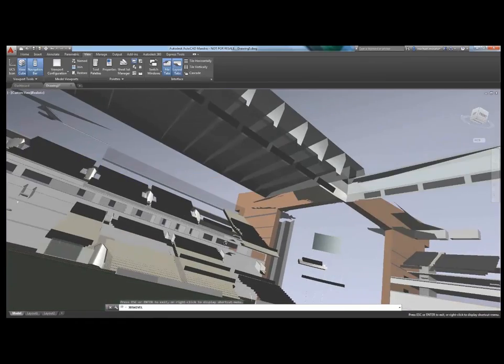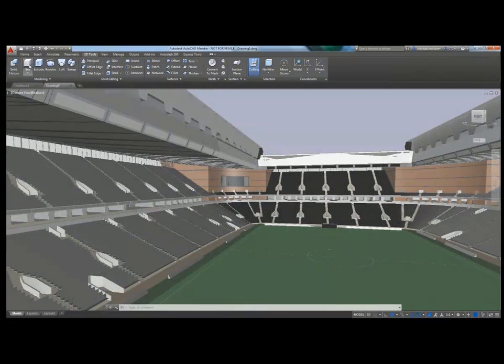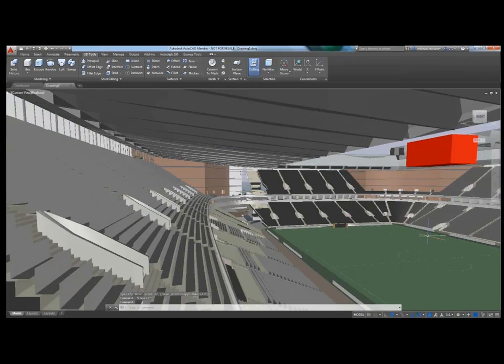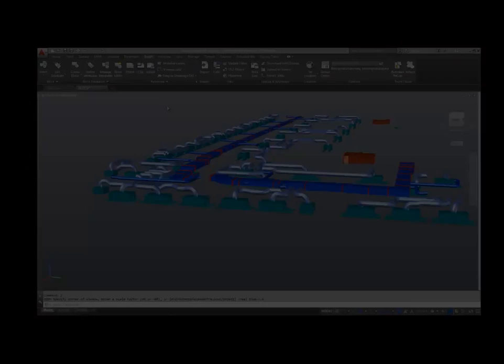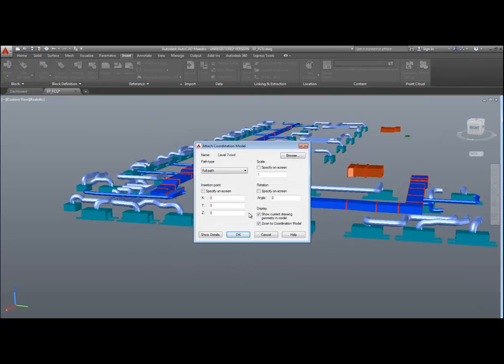So you can navigate through this model, and we also have the ability to include something on this drawing, to include more geometry. In this case, we can create a solid using AutoCAD features, and this solid will be included on the model that is brought from Navisworks.